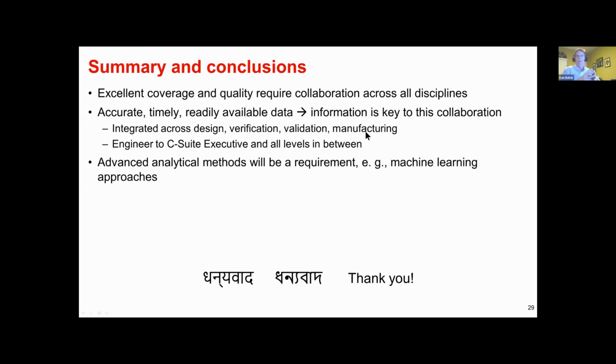Today that might be 21 sites across the wafer where you collect information from structures in the scribe lines and make performance measurements. You may measure transistor gain or sheet resistance and things like that. When you take that information, you can start with machine learning approaches to get a rough view of the wafer map even before you've done any wafer probe operations.